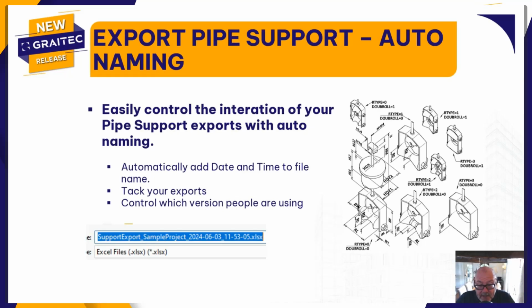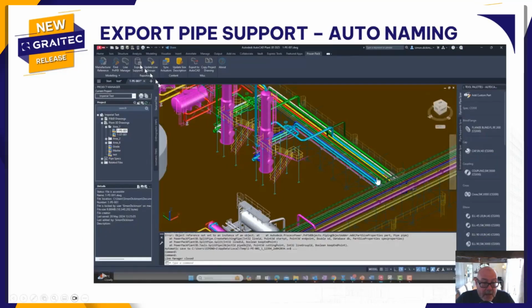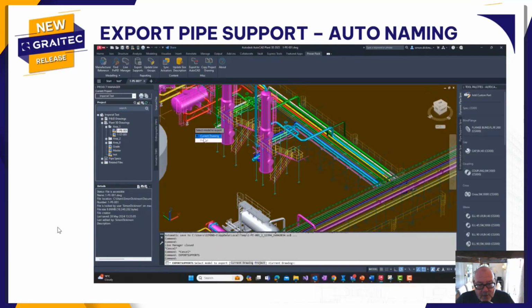If they've got the latest set of data, we can be confident that the fabricators have got the correct data for the files. So here we are inside of Plant again, on our exports pipes. Now what you will notice is this is fast. This is one of the tools. I go project, and it's going to export everything from a project.